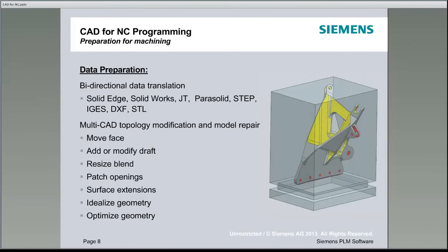With that, all of the data prep: you can import different CAD models, of course, and then you can build some stock models or blanks, or again, you could open those up and make changes to them. So we're going to go through this little aerospace wishbone type part, show you a way here if we wanted to make a little billet and a blank for it, and cover all those areas we did there, some modifications to the part, some optimization to it, build that, create setup assemblies, the drawings, etc. So we'll go ahead and take a peek at doing that here in just 1 minute.